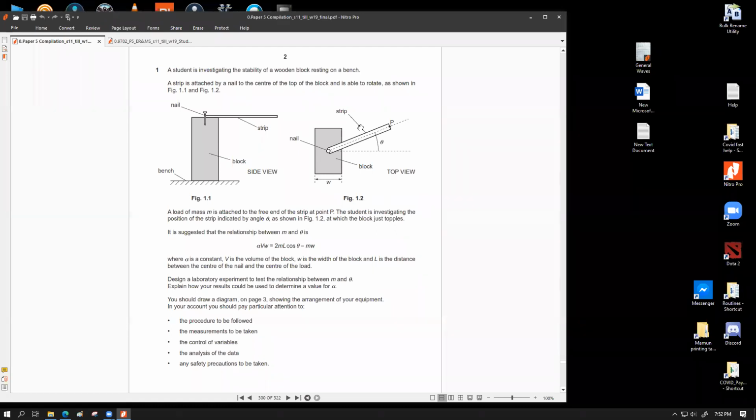You might wonder about one thing: for this experiment to work properly, there are a couple of really important things in play. You must place this block on the same surface, or the same location of the table, throughout your experiment, and that surface has to be horizontal. The surface on which you are working should not be tilted to any side, because that way you will have different values of turning effect. So having a spirit level to make sure that this bench is horizontal is a pretty important first step. And then we have to attach those masses.